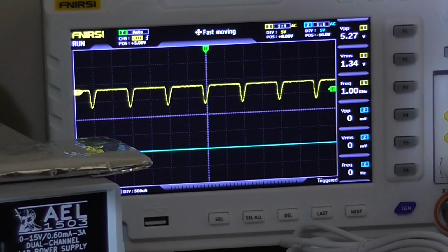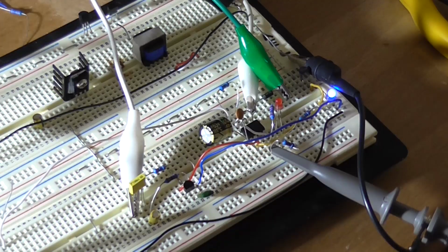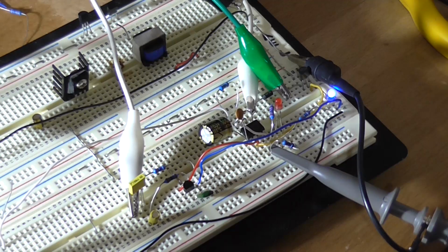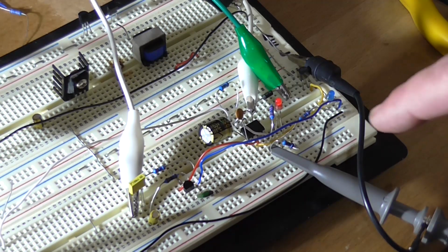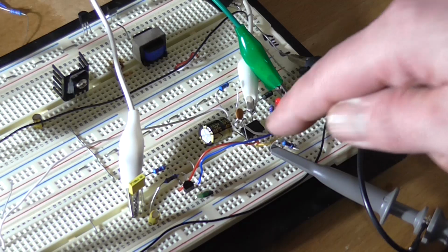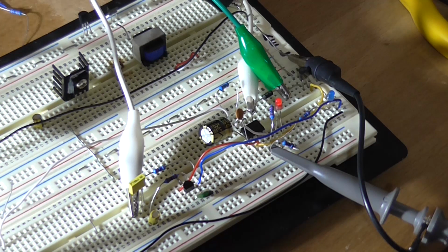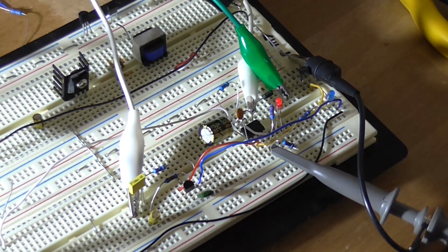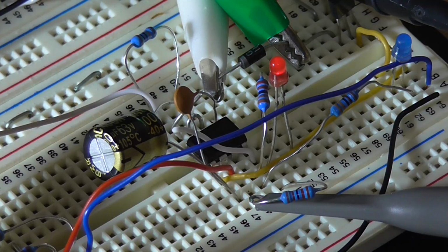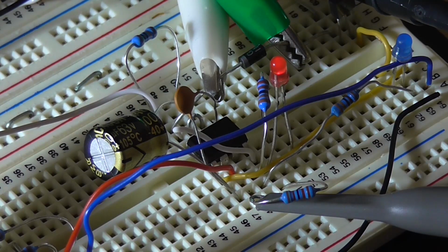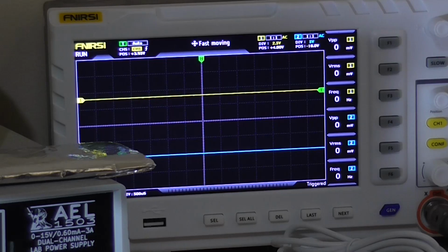it's still reacting too slow. And what I mean is that this is just not sensitive enough. So I reckon that this resistor may be too low of a value. So let me up that to 22K also and see if that makes a difference. Alright, the 22K resistor is now in place of the 1K. So I'll rotate the pot.